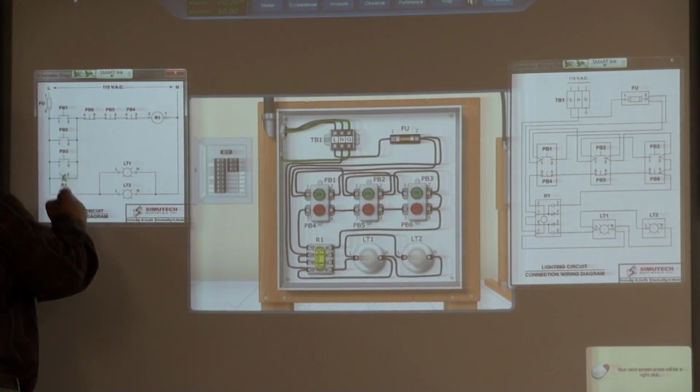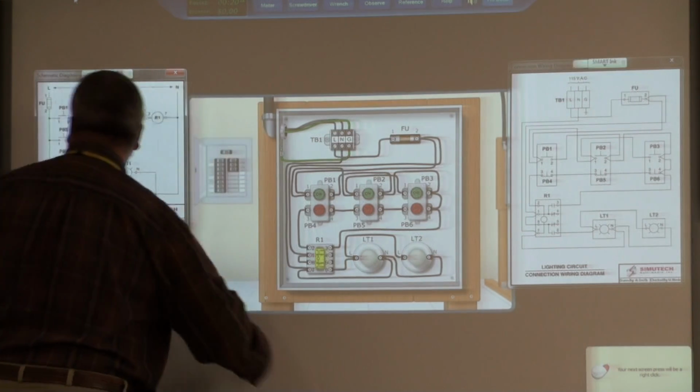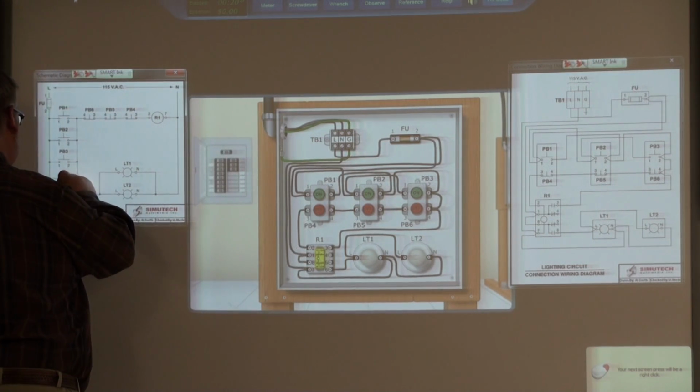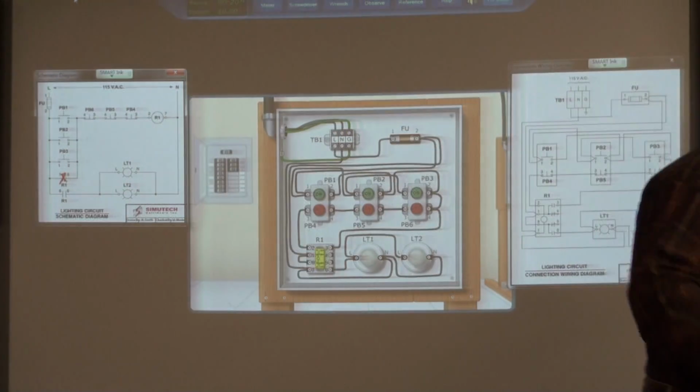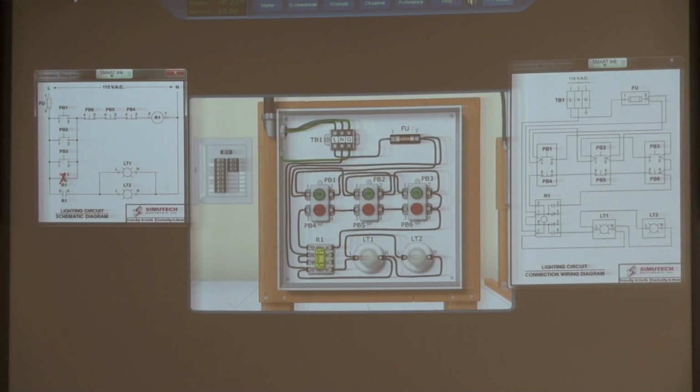This part of the relay goes bad. First, what are the symptoms? The coil will come on, but it won't latch. The coil will engage but not latch. Let off of the push button, and it's going to go off. That's correct.